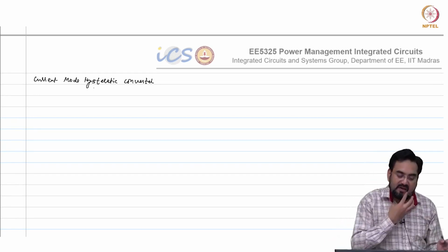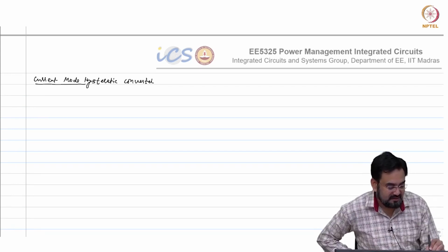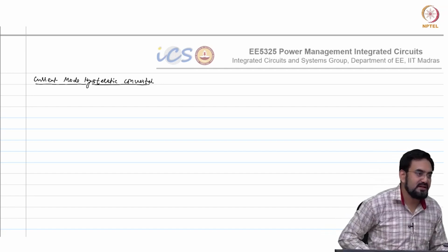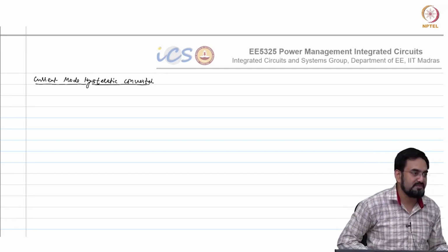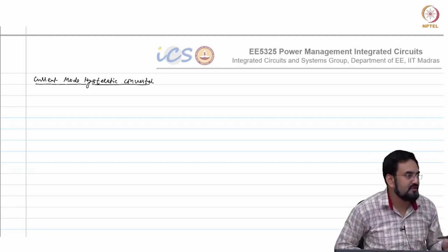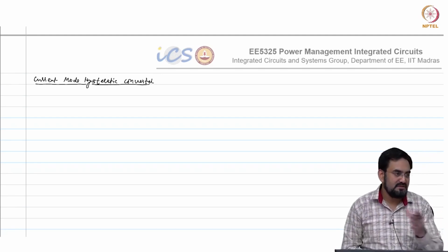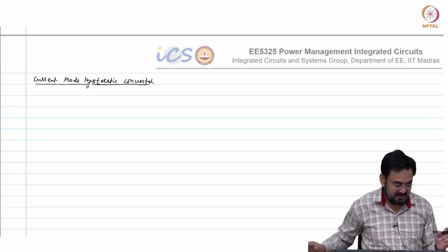So ripple we want in phase with inductor current, then why don't we just sense the current and generate the ripple out of that rather than relying on the output voltage, because we know output voltage is 90° out of phase from the inductor ripple current.